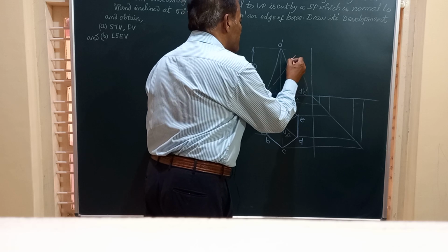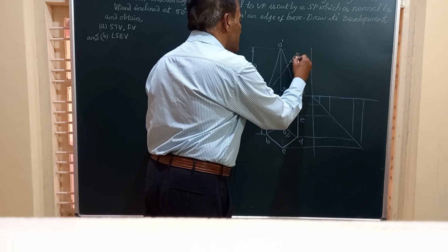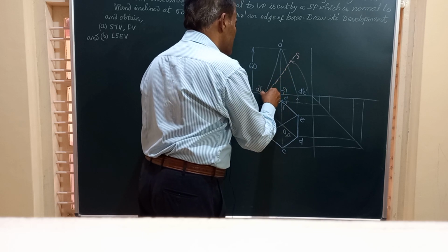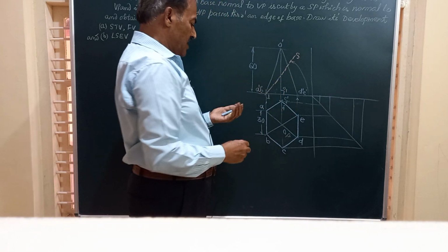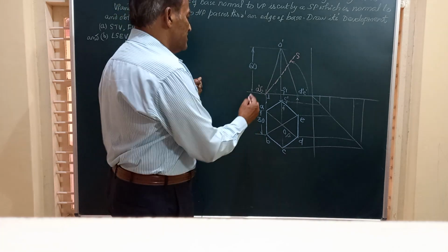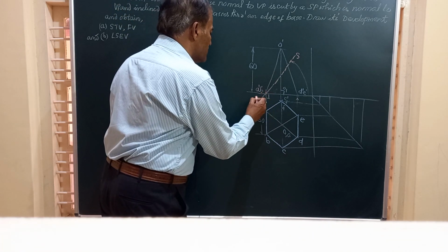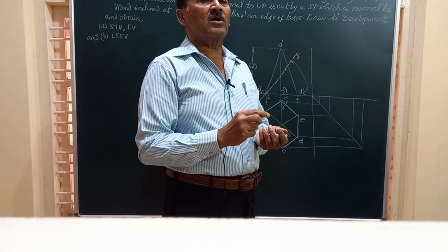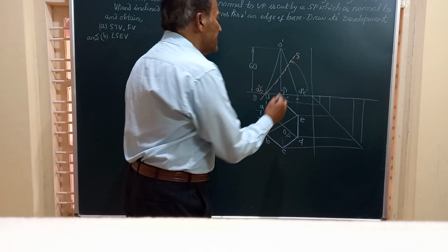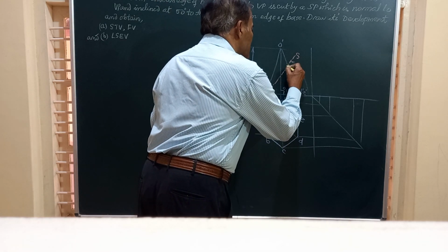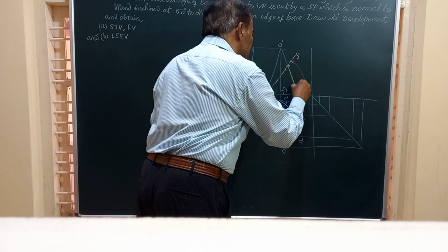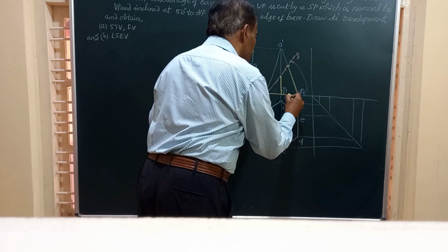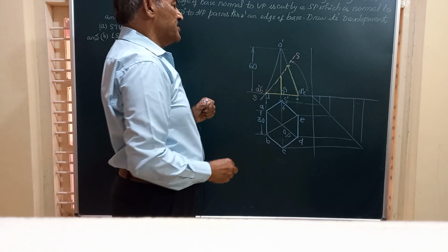And this is the section plane. Yes, I am going to show it dark, passing through the edge here. And friends, after marking the section plane SS, passing through AB, let us see what portion of the pyramid is retained for development. So this portion below the section plane is retained for the purpose of drawing the development.